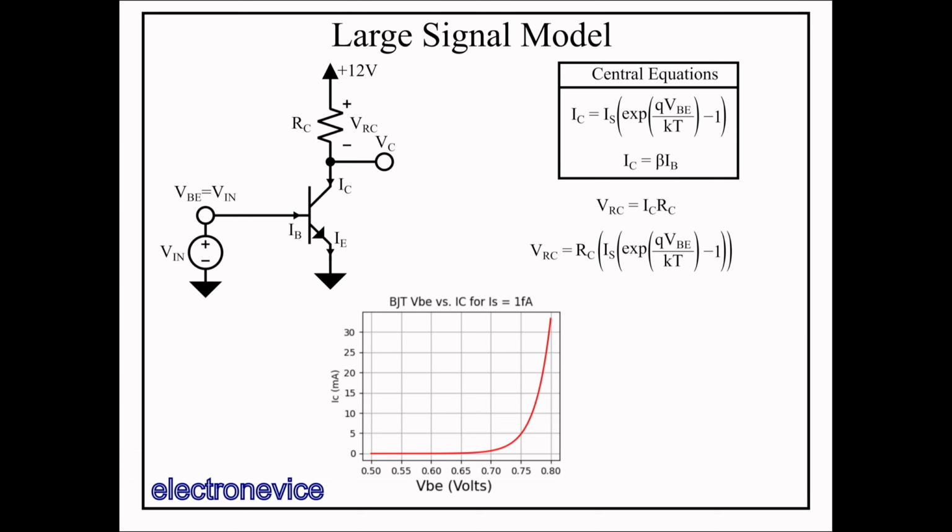So here's the exponential. Now we need to think of this circuit in terms of signals rather than just voltages. In this case, let's set our input signal as a change in voltage of VBE rather than just the total voltage. This is important because, as we can see from the plot of current, it's best if we can apply an offset voltage of about 0.6 volts before applying our input signal so that we can get significant collector current. Similarly, we set our output signal to be the change in voltage of VRC. This eliminates any offsets caused by the VBE offset we apply on the input.